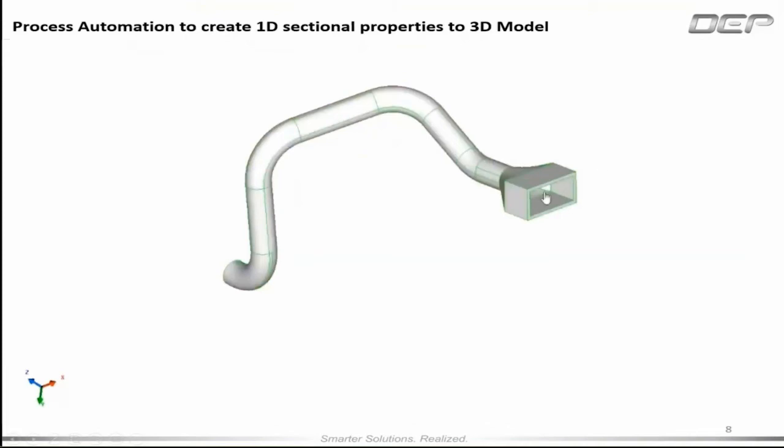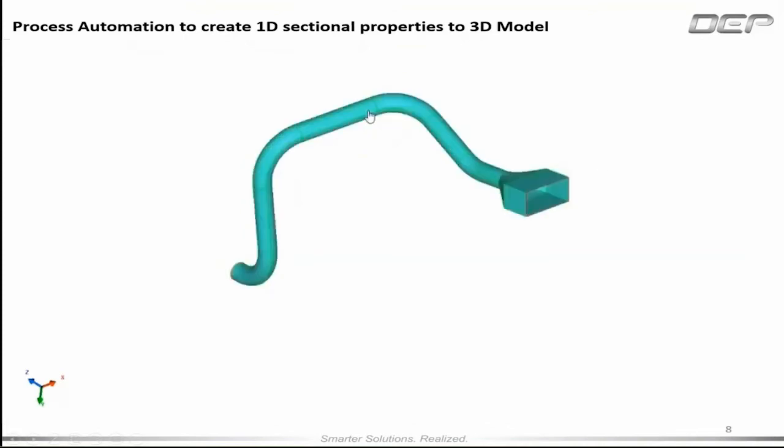So it nicely identifies the internal flow region, the wetted surface region, isolates it and gives it to you as an output. Then the user is going to select the CAD surface for meshing, where it needs to be enclosed for the simulation process and the parametric process. So we are just identifying the open ends and closing them. It just says open, close, and it gets closed.